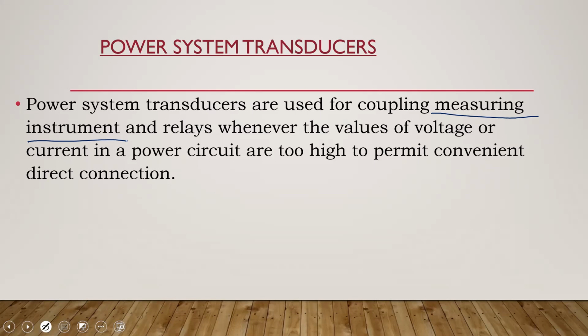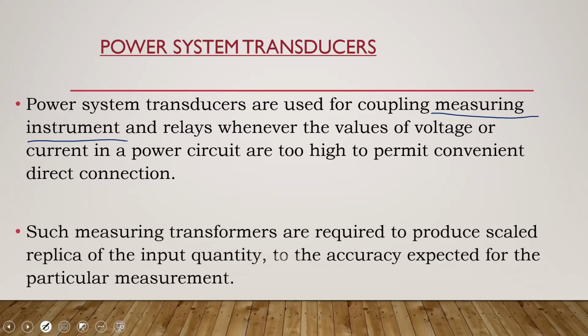Then you also have your CTs going to your relays, and as we said before, your relays help with the processing of the information and determine what happens. So your CTs, because you're now over your 200 amperes, you're not going to see 200 coming through the secondary. All it is doing is scaling that current value and giving you an output.